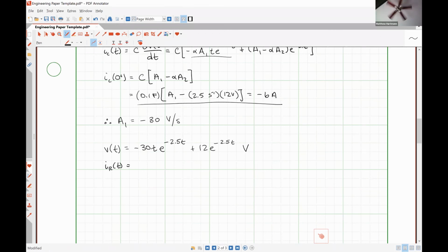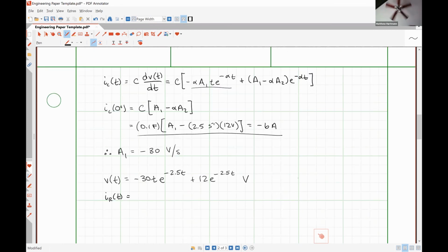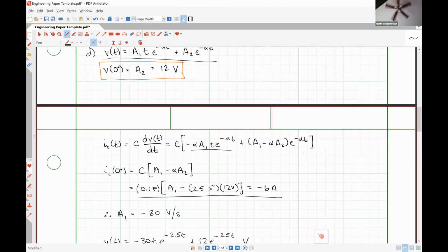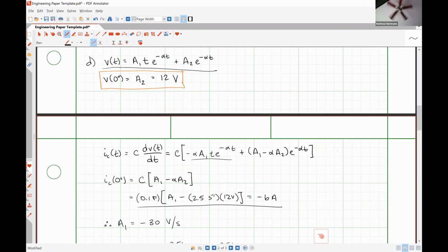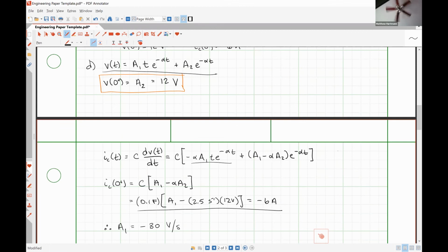So this is an important point about solving RLC circuits, whether they're series, parallel, or general. The relationships that we use to get an analytical expression for the voltage response, we were able to do that because we know that the voltage drop over the capacitor and the current flowing through the capacitor have a derivative-based relationship between them. They also have an integral-based relationship, but I don't like doing integrals, so I never use those.